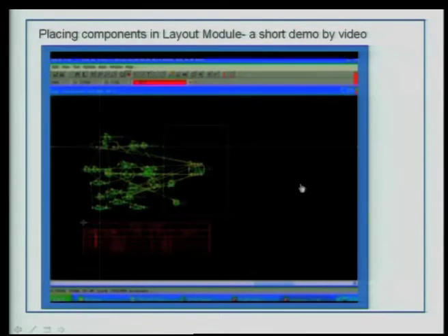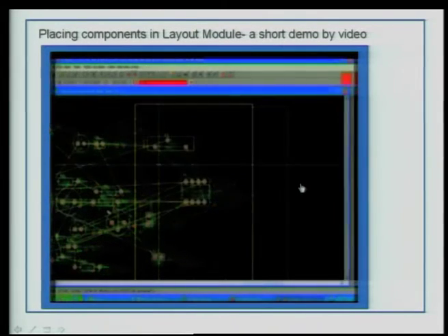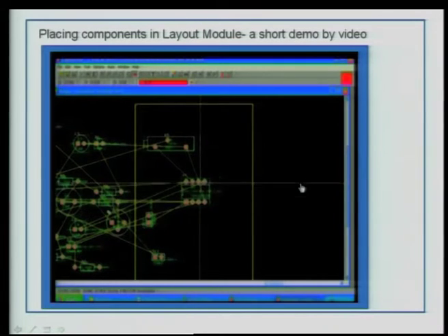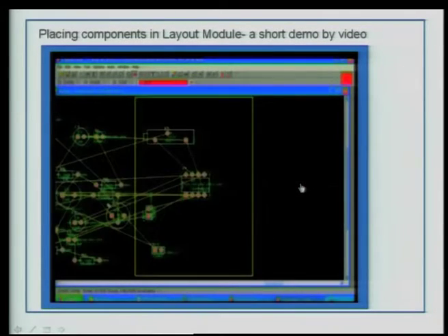So, typically as a good designer, what you have to do is mark the devices that you want in a particular area in the board, like a connector, or a varistor or a potentiometer that you will access very often after the board is assembled. Keep the critical devices at the center and then glue them.